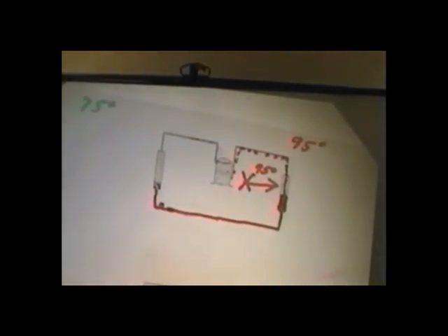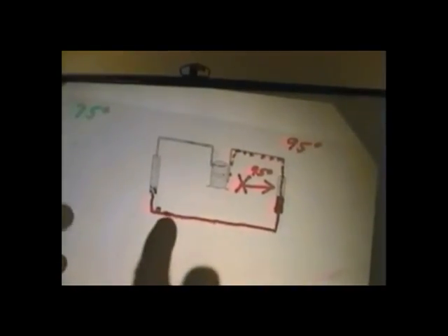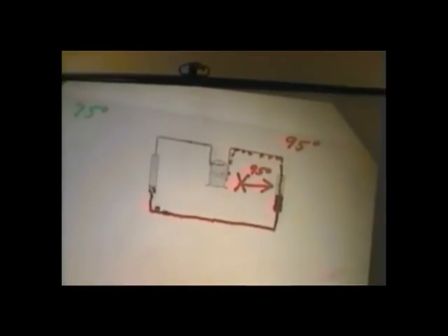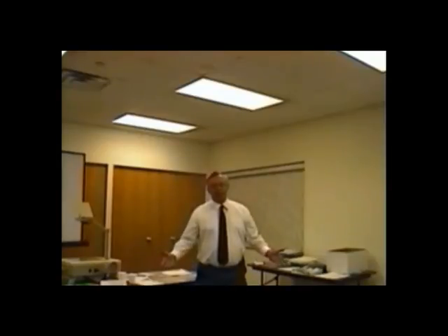But take a look at this, and we're going to stop here and talk about this for a minute. We have liquid in the bottom of the condenser, and the liquid goes all the way through until we reach the dryer, which is installed. The liquid dryer is installed in the place where it's most difficult to install, but it's the proper place. Inside the home, right before the metering device. It's a filter, it's a dryer. It's supposed to keep contaminants out of your metering device.